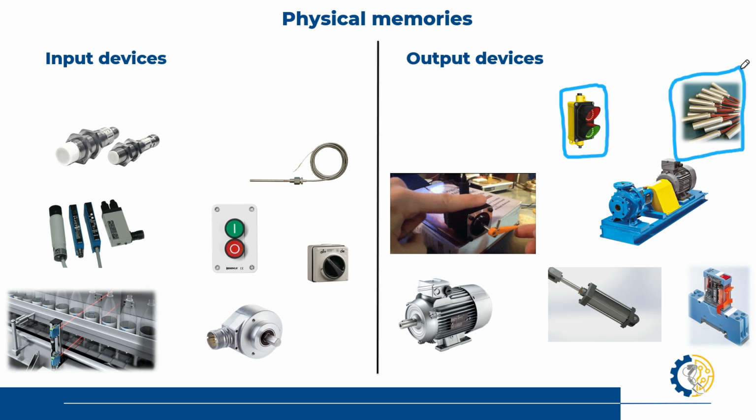We can send a certain voltage, these are generally voltage, but then we would send it from 0 to 10 volts, or 2 milliamps, or 4 milliamps, depending on the output type that we have for our PLC, or whatever output is sending for our coil.